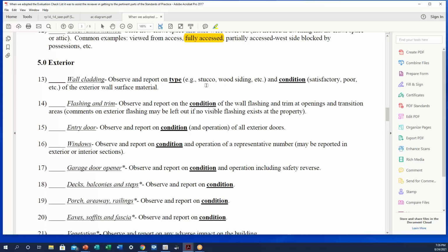Yeah, there's 4 or 5 different types of stucco. So they want to know, are you going to tell me what kind of stucco it is? So is this an acrylic stucco? Is it a cement-based stucco? You don't have to say Powerwall, that's a brand, but the acrylic stuccos come out of a can and they're troweled on. I don't see much of that. Or EIFS. We don't have much EIFS here, but back east, that's everywhere. The energy efficient stucco systems, EIFS.